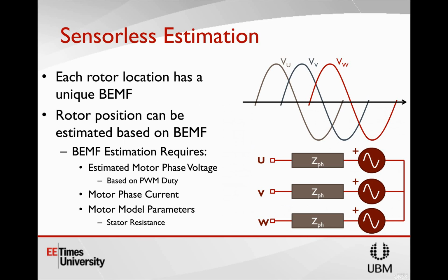What high-frequency injection does is it places the iron inside the core of the rotor, the magnets, into saturation. What you're trying to do is look at the subtle differences in the magnetics of the rotor for the D-axis and the Q-axis. So you're doing a high-frequency injection and looking for the subtle differences you see in how the rotor responds on those two different axes. It is based on not having perfectly symmetrical inductances inside the motor. So it assumes you have some amount of difference between your D-axis inductance and the Q-axis inductance.